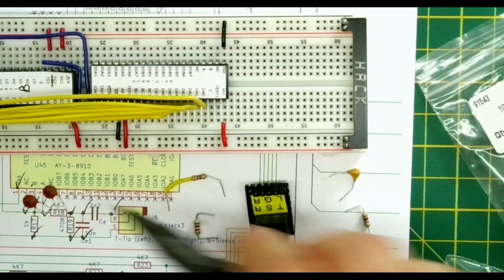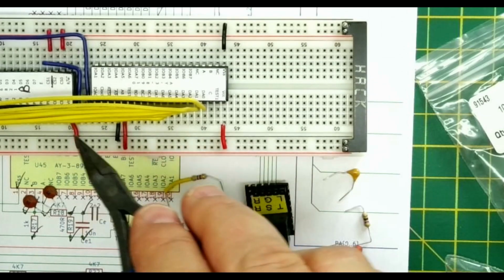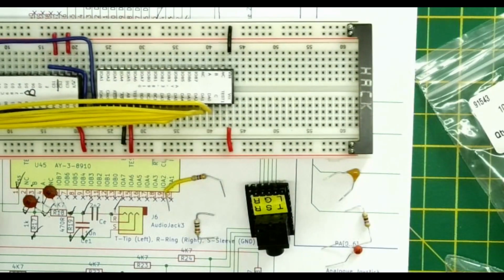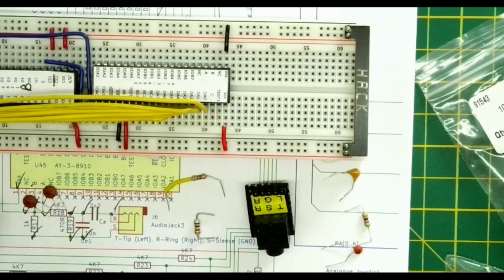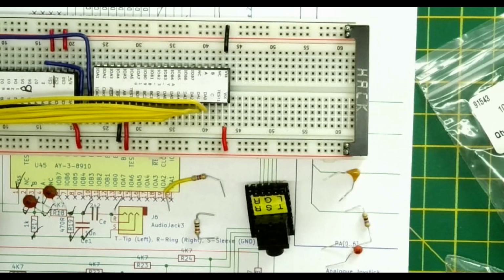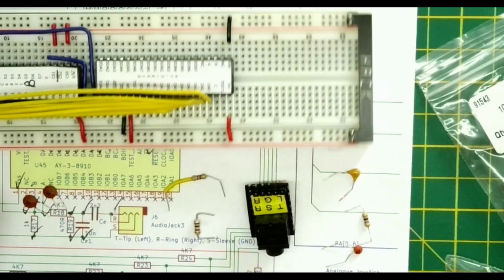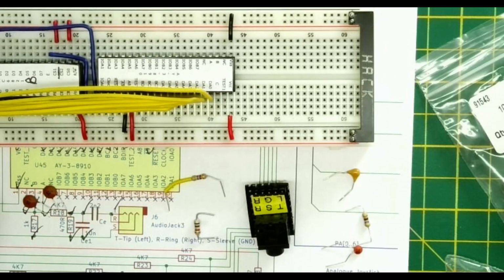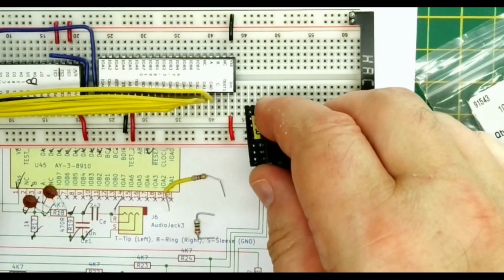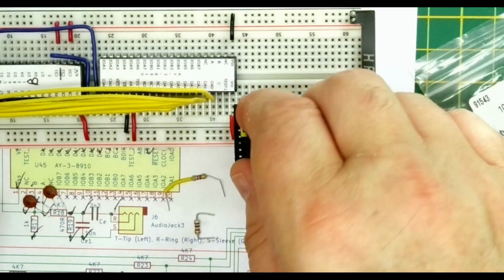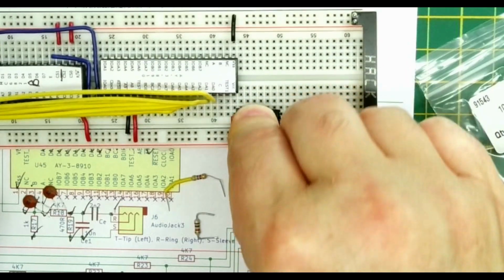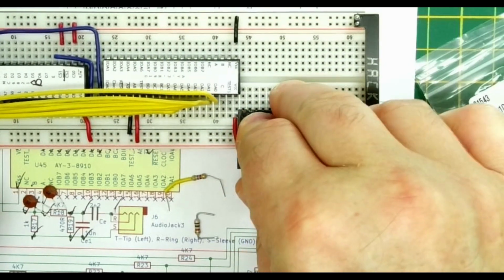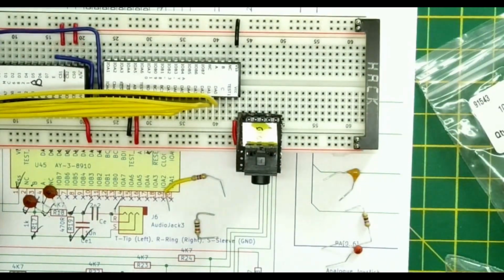Okay, so we've done the digital side of the circuit, apart from hooking in the bus signals and things to the PS2 keyboard controller and the rest of the Nanocomp. So we're just going to do the analog signals now, so that's wiring up A, B and C over here. So I'm just going to plug in the connector first. This should just hang over the board so it makes it sort of nice and sturdy.